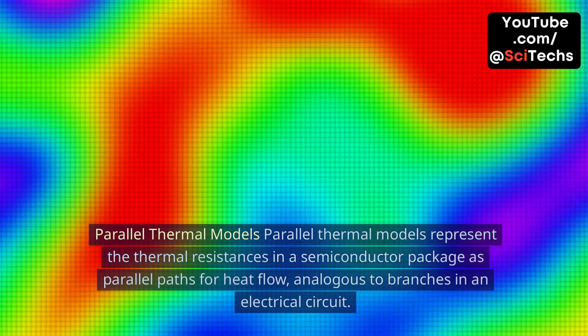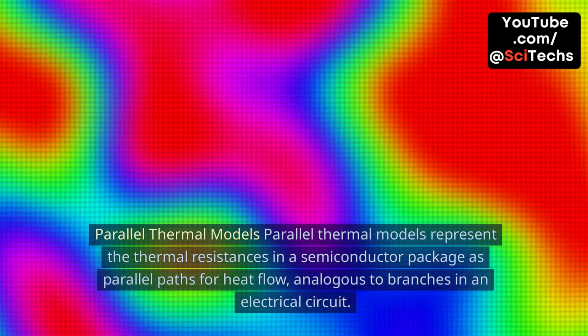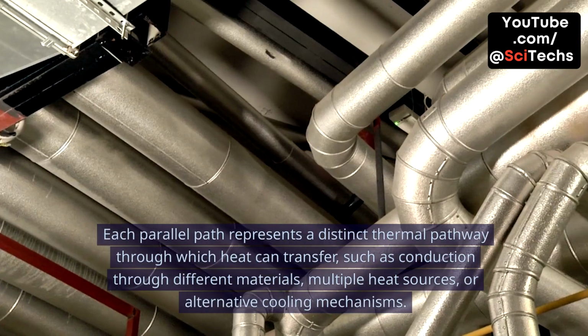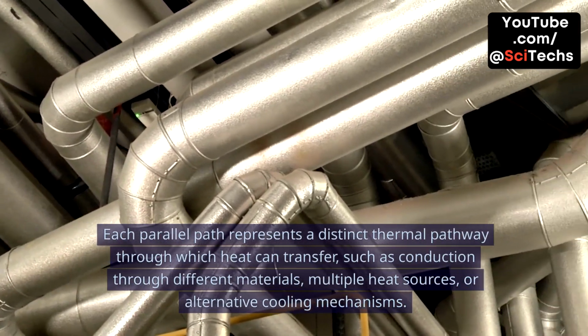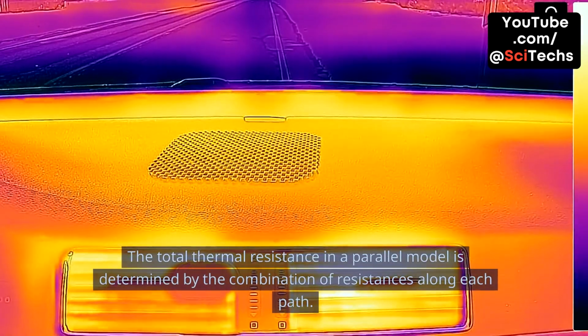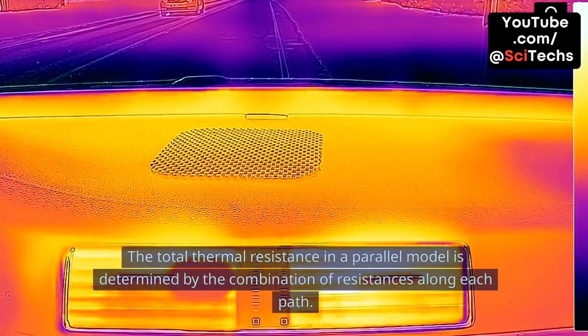Parallel thermal models. Parallel thermal models represent the thermal resistances in a semiconductor package as parallel paths for heat flow, analogous to branches in an electrical circuit. Each parallel path represents a distinct thermal pathway through which heat can transfer, such as conduction through different materials, multiple heat sources, or alternative cooling mechanisms. The total thermal resistance in a parallel model is determined by the combination of resistances along each path.